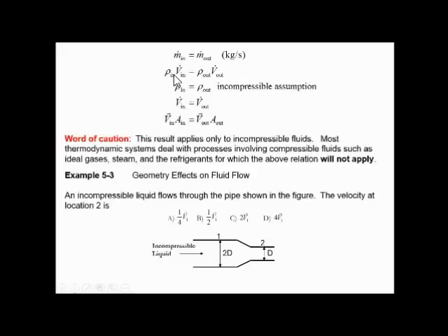Substituting the rho and volume terms, we get this. And if the density rho in equals rho out, that means it is incompressible. As we have considered this special case, the fluid is incompressible. So what we get is V dot in equals V dot out, that is the rate of change of volume going into or coming out of the tube. This V dot can be further written as velocity times area of input and output respectively.